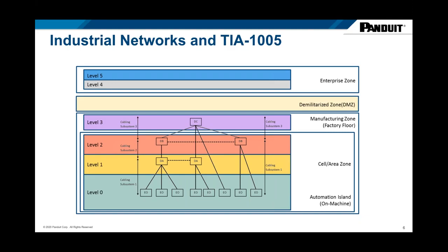The structured cabling environment lives in conjunction with and is the connectivity system for the industrial compute platforms that might be at level 3, where your servers and storage might be for your manufacturing plant floor. And then your intermediate distribution frames or your switches out on the plant floor that are helping control that copper run distance and providing you the right level of bandwidth and communications, those are at level 2.